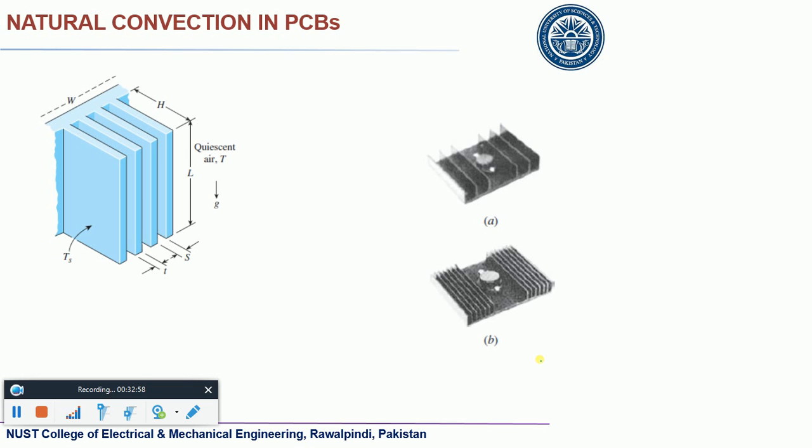It would provide you more surface area, just like the fin definition. You remember that we talked about those things in the fins. So what do those fins do? They basically provide you more surface area, and you can have more heat transfer if you have more surface area. But the thing is, this lower configuration might not allow you to pass more and more fluid through it. So if you have more surface area, you would have more friction as well.